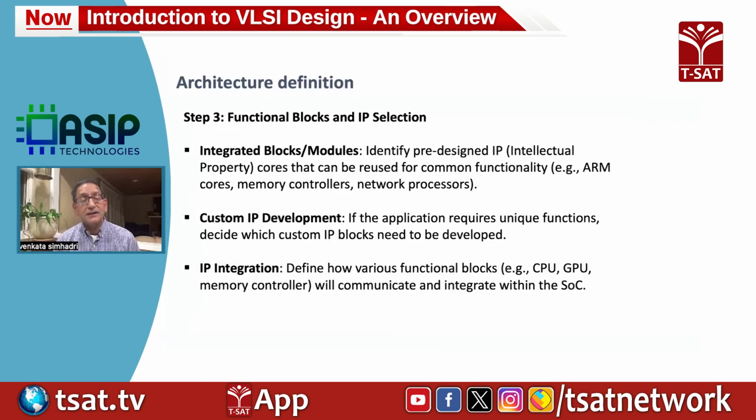And step 3 is identifying all the functional blocks and IP selection. So nowadays nobody designs every block that is used in the SoC by themselves. Most chip companies or SoC companies license the pre-designed IP blocks. For example, if you're using an ARM CPU, you can license that CPU from ARM and just drop it in your design. Similarly, if you have a PCIe interface in your design, you just license it from companies like Synopsys or Cadence and drop it in there.